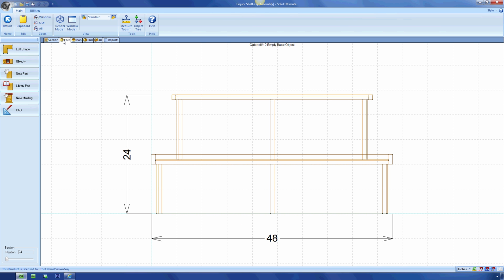On top of the added parameters, I actually created a couple of new parts in my part catalog. The skin top finished and skin face finished. The logic is a bit different as well, not just changing the names for the parts. For instance, where we set the skin left finished for our top skin to have a y of :cab.dy minus _m:dz, I used :cab.dy minus dz.